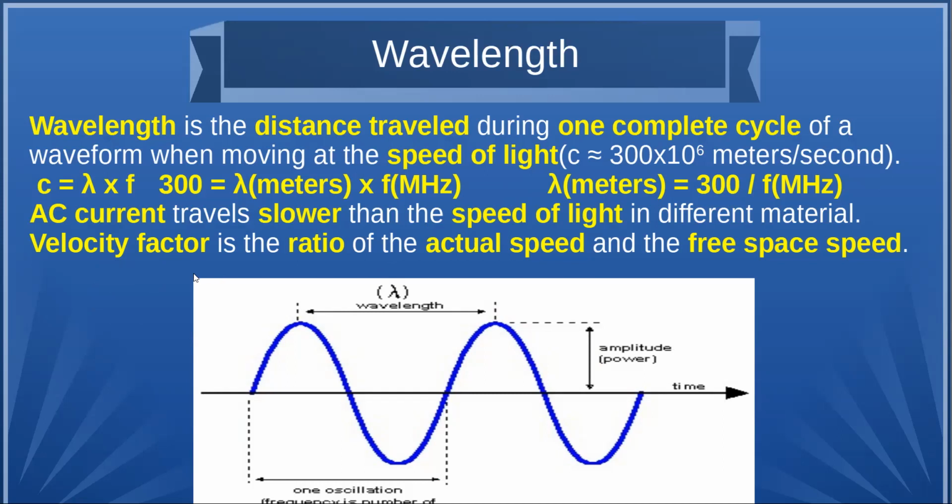In other words, what percentage of the speed of light is it actually traveling at through that conductor? In coaxial cable, sometimes it's as low as 0.75 of the speed of light. So you need that correction factor, or else your length measurement for the wavelength is off. And in fact, for one of the exam questions, you can get the right answer without doing the correction factor.